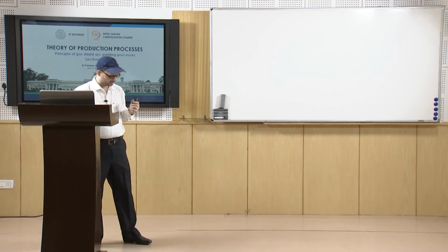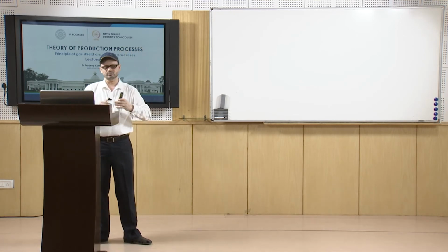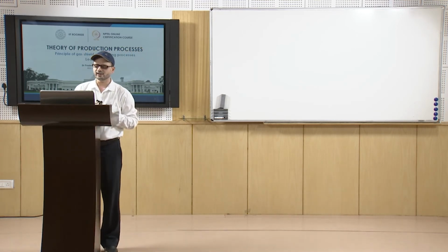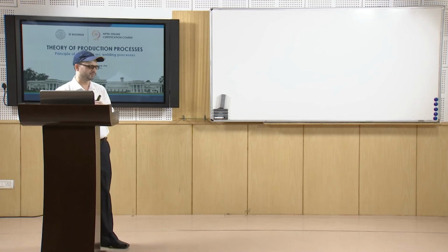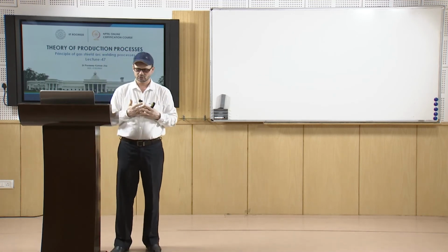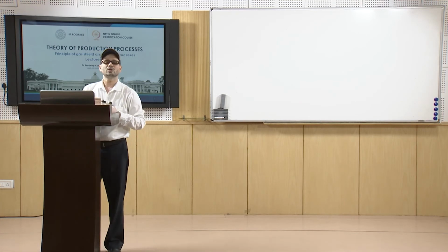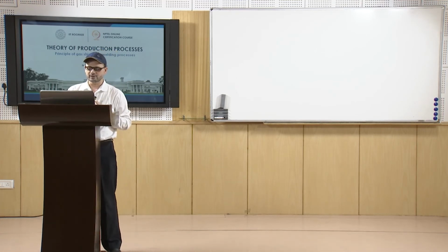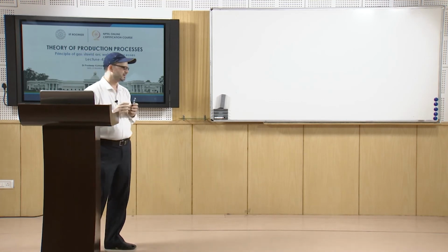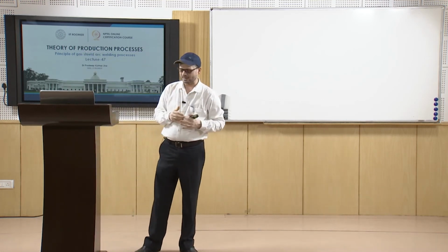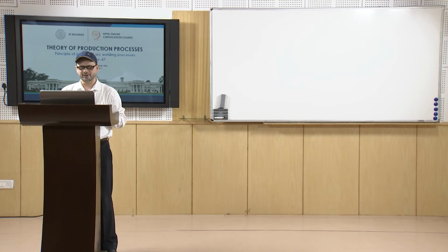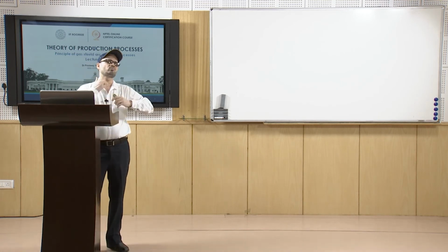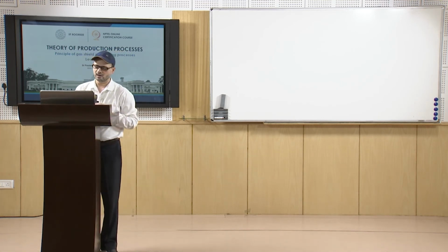Now, as we discussed in the past, even carbon dioxide is one of the very favorite shielding gases used for welding ferrous metals, because of its large inexpensiveness. It is quite cheaper as compared to the other two gases. Basically it is as cheap as 1/10 as compared to either helium or argon. That is why many a times we use carbon dioxide as the shielding gas.